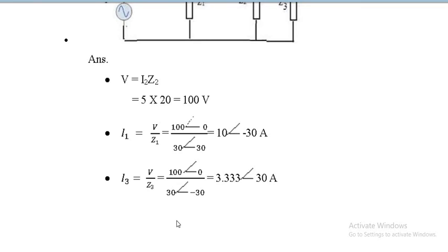So parallel circuit problems are actually very easy. Simple mathematical operations are there. You just have to do it very carefully as far as R to P and P to R conversions are concerned. Mind well that whenever it is addition and subtraction, you will always have the phasors in rectangular form, and whenever it is multiplication and division, you will have to use the polar form. Just remember it, and also remember that the final answer has to be in polar form.